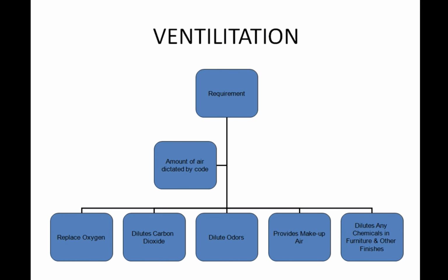that you're removing any of the odors or chemicals that may be in the air, that come from carpeting. We all have heard VOC, volatile organic compounds. Those are what basically create the odors, and with those odors come chemical levels in things like paint, carpeting, finishing for the floors or windows. Any of those chemicals may have a VOC level, and if you're doing green building, you'll have a very low VOC level, or use materials that have no VOC. So then you don't have so much of an issue of those things polluting your air, but you still need to exchange the ventilation, remove carbon dioxide, and replace with oxygen.